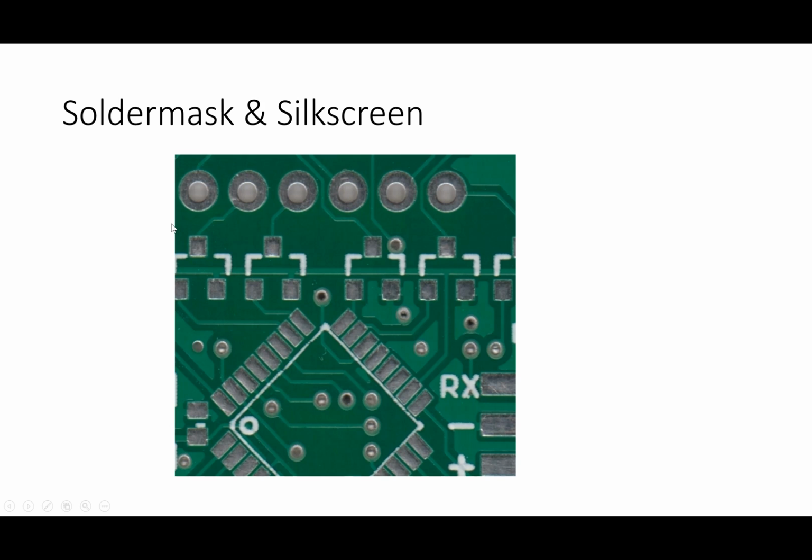So essentially what's been done is the solder mask has been laid on top of the top layer, and wherever it crosses over copper, you get this lighter color. These darker areas are just open board. That's basically just the solder mask sitting on top of blank FR4 substrate. So a couple of things here. I said these are plated through holes. These plated through holes right here, with these big annular rings around them, you can solder to.